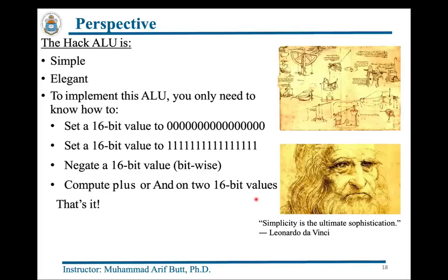And let me say, dear students, that the design of this Hack ALU is really simple and elegant. To implement this ALU, you need only to know how to set a 16-bit value to all zeros, how to set a 16-bit value to all ones, how to negate a 16-bit value, and how to do a plus and an AND operation on two 16-bit values. And that is it. So it is really a very simple and elegant design.